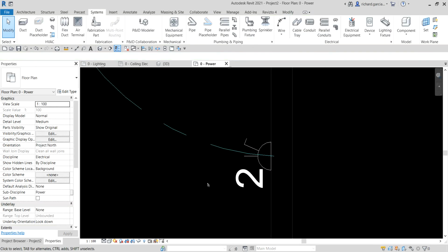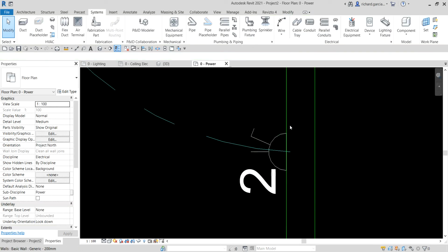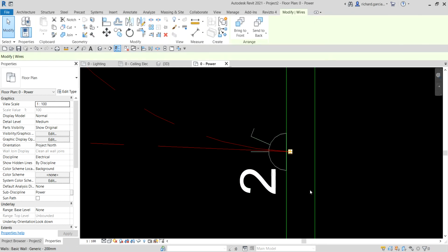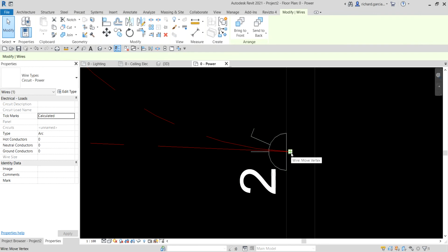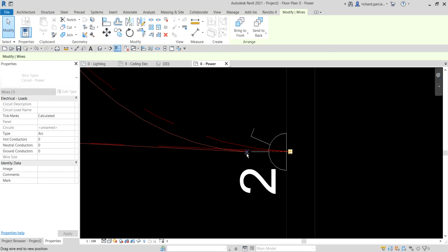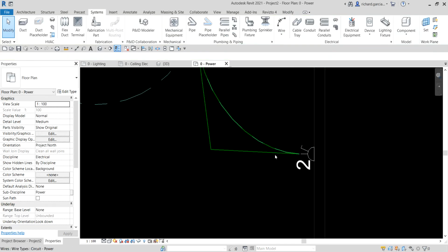So if you want to tidy it up, you don't want highlighting or overlapping your socket here. So you click the wire, hover your pointer, press tab once. Once you see that circle, you move the wire to tidy it up. There you go. So it's still connected.